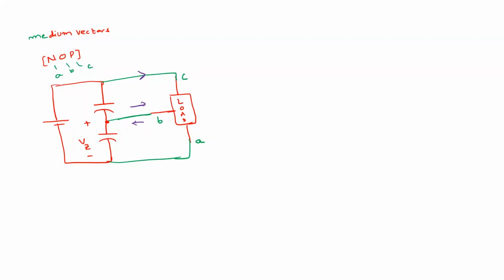Therefore, the current may charge the capacitor, or the current may discharge the capacitor. It will affect the neutral point voltage. So here the current is flowing either into the neutral point or away from the neutral point, but definitely it is affecting the neutral point voltage, right? How it is affecting is undefined. So here Vz is affected, but we cannot determine that. So that means not determined, or in other words, not defined. We cannot comment on whether it is increasing or decreasing, but definitely it is affecting.